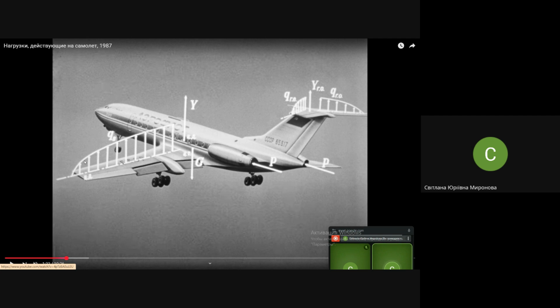As I said, it results in some lift force, and this lift force is the aerodynamic load. Here we see the distribution of these aerodynamic loads. Altogether, they may be represented as an equivalent force acting at the center of pressure of the airplane as a whole. All the forces acting on the stabilizer, the wing, wherever, with respect to the center of gravity, and additional forces which appear due to engines, in this case thrust.